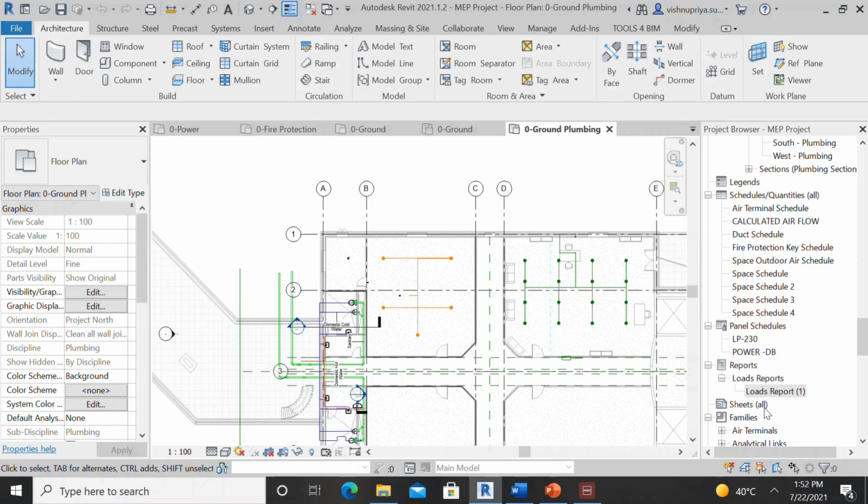Navisworks is mainly used for clash detection, but there are some extended options for 4D and 5D in Navisworks. Now what I explained about BIM is everything which is BIM 3D. The next stage is BIM 4D and BIM 5D.